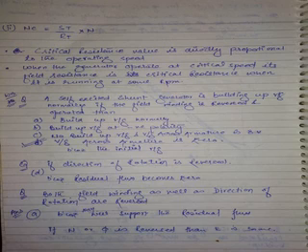Next, you reduce the speed of the generator to 1000. So what is the critical resistance? Again, you have to plot a tangent somewhere here. So make it. So what happened to critical resistance? Decreased, right? So what is the conclusion now? The critical resistance of the machine depends on operating speed. NC is one value for a machine, 900 is one value.